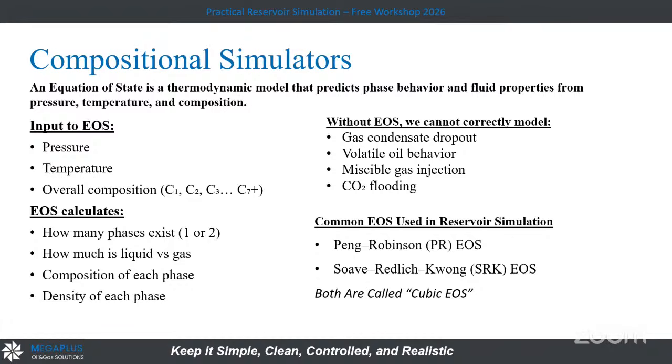The compositional simulation, as I mentioned yesterday, deals with very massive equation solving. In each time step or each pressure, we have a lot of variables that change. The inputs of the equations we made in the homework before we made the model, or I have to insert some parameters, you will see in the next slide. The input would be the pressure and temperature and the composition of the fluid at each pressure and temperature. And the equation of state functions will calculate how many phases exist.